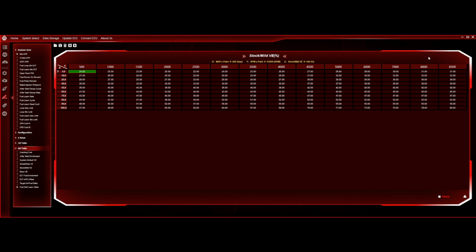This isn't an actual volumetric efficiency table of your engine. This is the best guess that you can get to based on what AFR numbers you want and how the engine's reacting. It's pretty accurate, but I don't think these are the actual volumetric efficiency tables. The factory has those for engines, and I don't think you can really get your hands on them. But as far as I understand it, and I'm still learning, the lower the number is, the less efficiently your engine has filled with basically oxygen dense air.